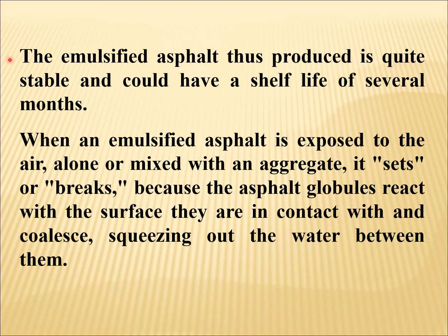The emulsified asphalt thus produced is quite stable and could have a shelf life of several months. When an emulsified asphalt is exposed to the air alone or mixed with an aggregate, it sets or breaks because the asphalt globules react with the surface they are in contact with and coalesce. That means they develop a collective mass, squeezing out the water between them.